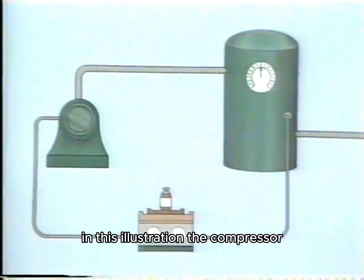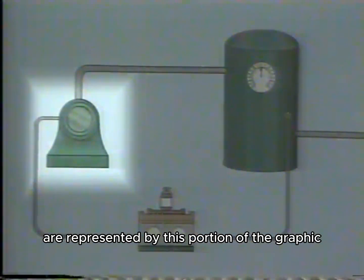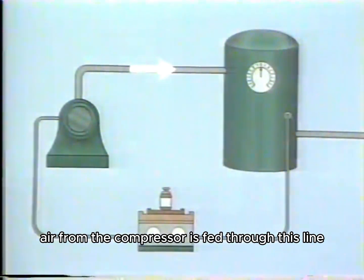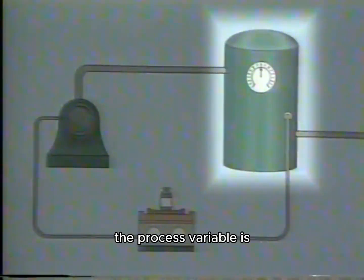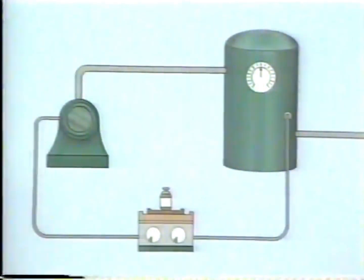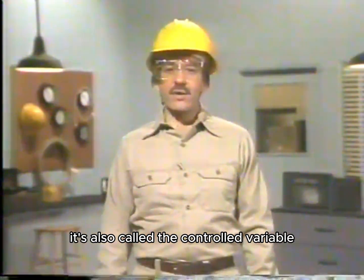In this illustration, the compressor and motor are represented by this portion of the graphic. The compressed air from the compressor is fed through this line and into the receiver. In this air pressure system, the process variable is the air pressure in the receiving tank. Because air pressure in the tank is the variable we want to control, it's also called the controlled variable.